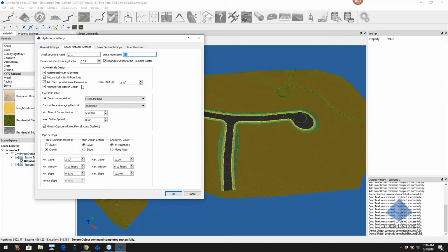Now, one thing that I do here in North Carolina is that on sanitary sewer, I'm allowed 2.4 feet of free drop inside a manhole. I don't differentiate that between storm and sanitary. So I'll just go with that 2.4 feet. I can adjust it later, but for me, for the time being, let's roll with that.